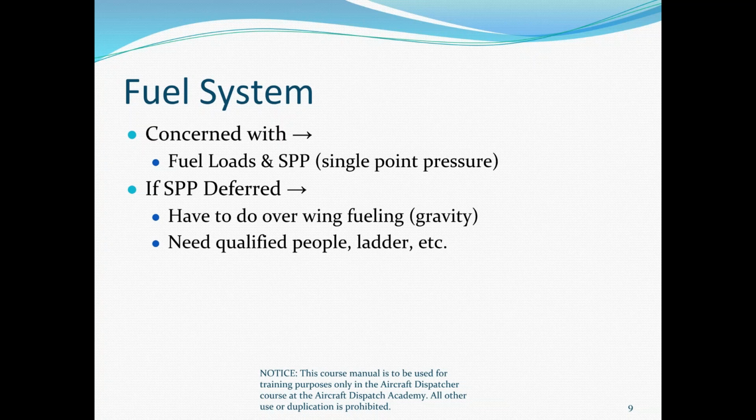And then you also need qualified people, stuff like that at the station. So if you're operating in Fargo or International Falls or, what's CMX? I can't remember the name of the airport. Houghton. Yeah, Houghton. Places like that, you may want to have the controller double check that they have the ability to do over the wing fueling, because that is a special certification.